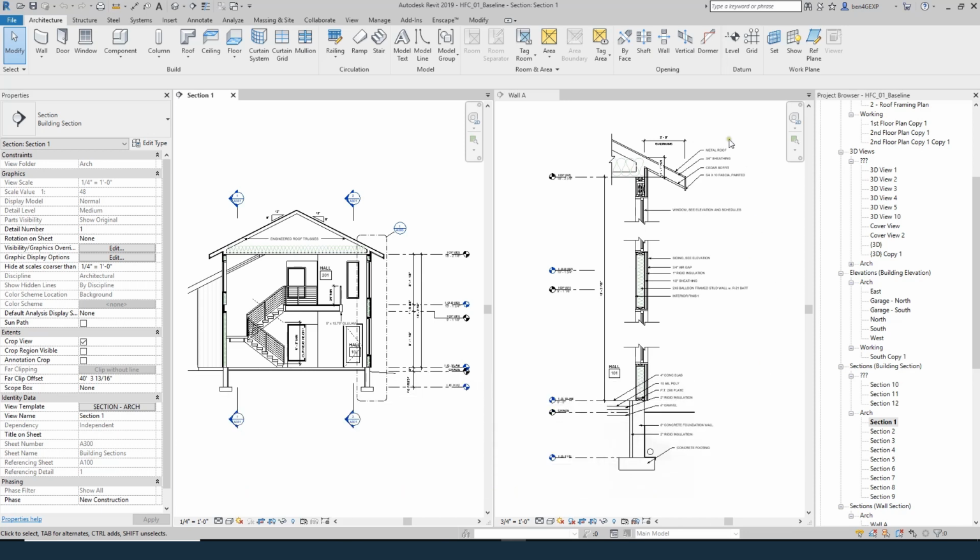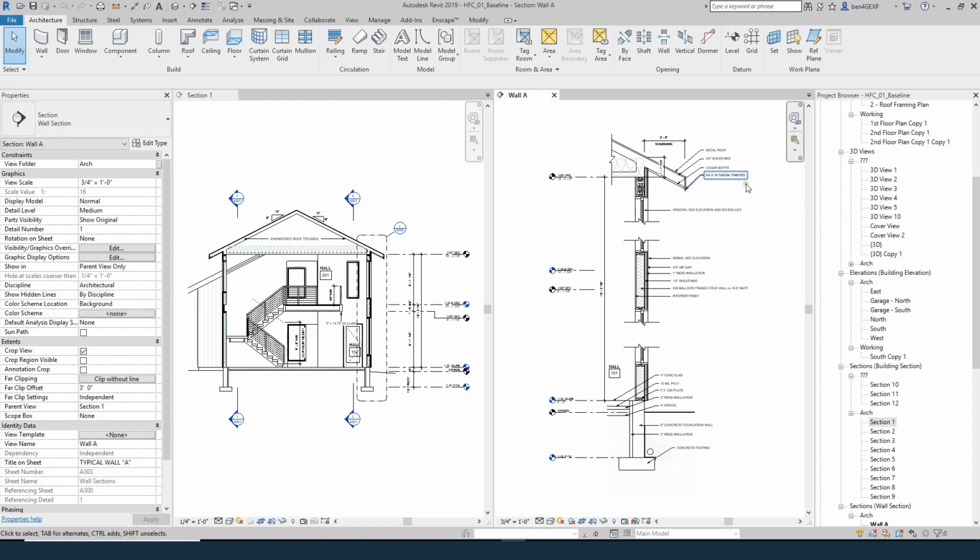And we use this to show the different layers of the roof, the wall, the foundation, how those things interact. So I'll show you how to annotate this, what information we need to show, what things we need to annotate, what we need to do sort of as drafting field regions, a couple ways we need to update our physical model in Revit to sort of account for some of these things, and generally what are the architectural and construction concerns when we're talking about our exterior wall.